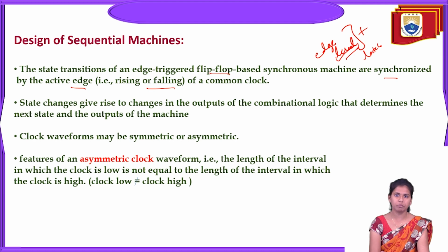Whereas edge sensitive elements are those where the output can be changed only because of the synchronous transition of the signal with respect to the inputs. So the state transitions of edge-triggered flip-flops in synchronized machines are synchronized by the active edge, based on the rising or falling edge of the common clock.